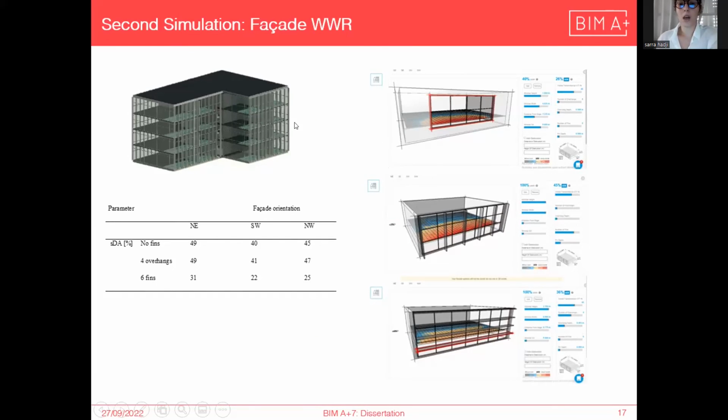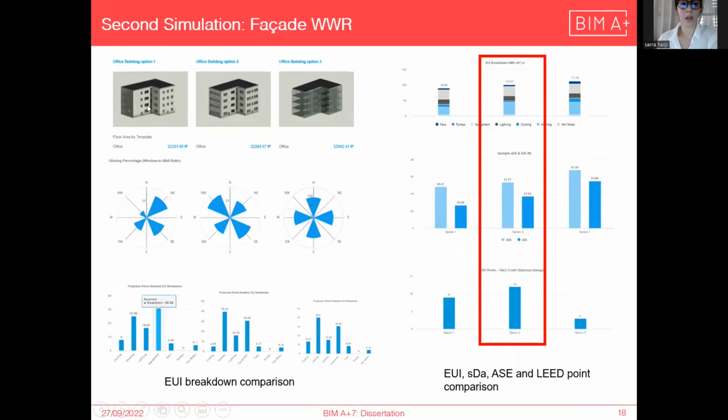But before that, I used a real-time simulation feature in the Cove tool to compare directly in real time which facade system I'm going to use, the dimensions of the openings, the fins or overhangs, the number, etc. And then I could take it to the next step and compare 3 types of facade systems, and same as before, identify which one helps reduce the energy and provide more comfortable indoor space.